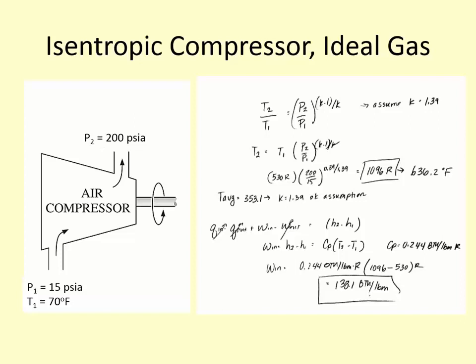Okay, so where do you find 1.39 for the K? Okay, so you don't know initially. You say, I'm starting at 70 degrees. How high is the temperature going to go? I don't really know, but my understanding from previous problems is, let's say it increases by 600 degrees. So you say, I'm starting at 70, I go up to 700. Then you look at those two lines on the table and find the average in between. Like the average between 1.4 and 1.377, we'll say, let's just use 1.39.